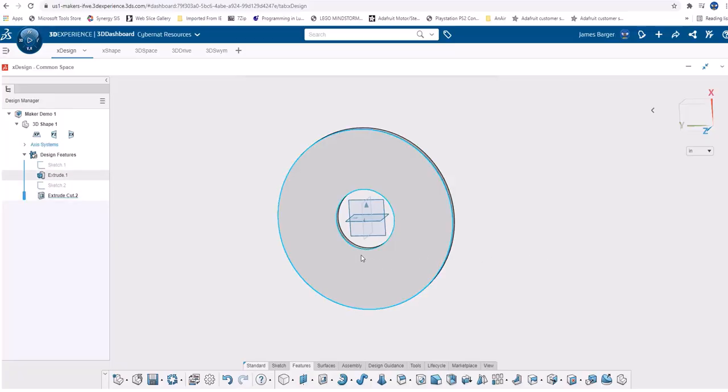I can also set that hole. I set it for 1/8 of an inch, 0.125. I could also have come down under Features and used the Hole tool or Hole command, where I could have selected a countersink hole, or a variety of different holes to cut. For what we were doing here, it was just as easy for me to sketch and draw a circle and extrude cut it, because again, we're doing a basic process here. So I have my washer or my spacer, whatever you call it. I've got it ready to go.